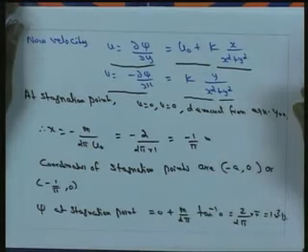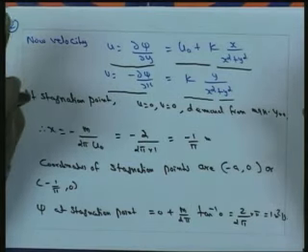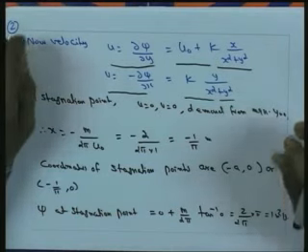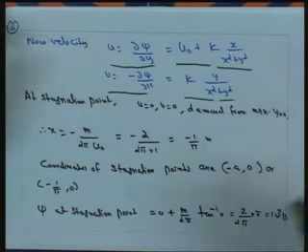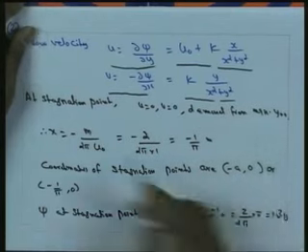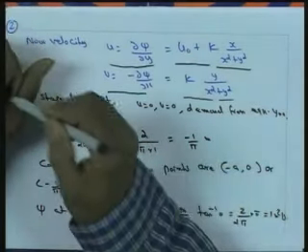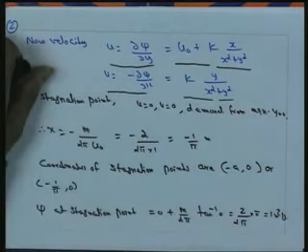So, thus we got the expression for velocity in x direction and the velocity in y direction, u and v, from the obtained expression of stream function with respect to the superposition of the uniform flow and source for the half body which we considered here. So, now as per our definition of the stagnation point, the velocity should be 0 at the stagnation point as defined here. The stagnation point is shown here. So, for stagnation point u is equal to 0, v is equal to 0.